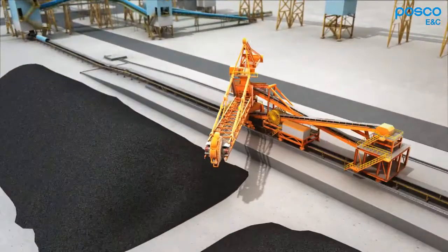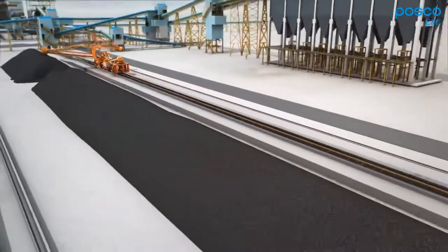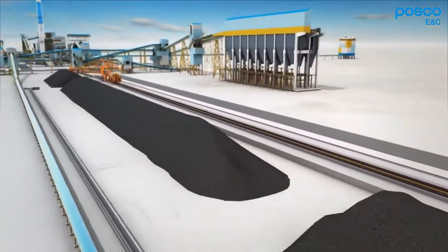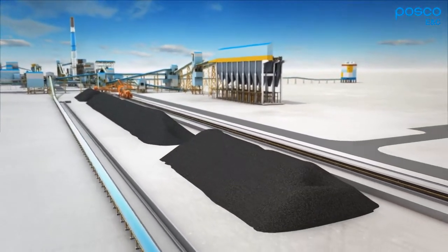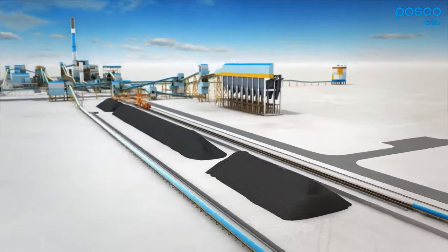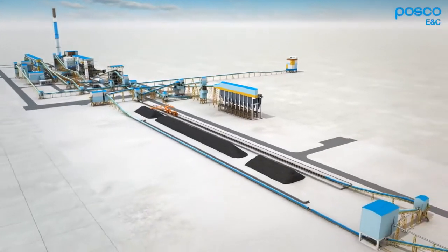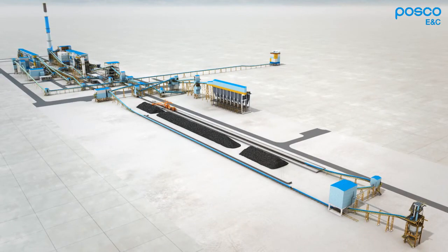In preparation for emergency, the sinter yard can store an amount of the sinter ore which can be used for the blast furnace for 2 to 3 days. In case the sinter plant has to be shut down, or planned repairs are required due to emergency during the normal operation, the sinter ore in the sinter yard is discharged by the stacker reclaimer and transferred to the stock bin again in order to keep normal operation of the blast furnace.